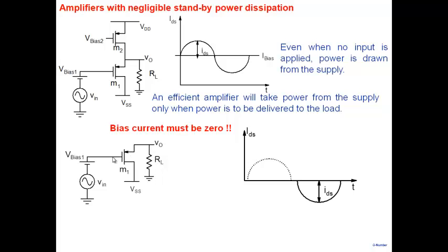If I make this voltage below Vt, right? So for a while in the negative cycle, you see it doesn't conduct. Once the voltage here, Vin, goes below Vt, then it starts conducting. And once it starts conducting here, what we have is basically a common drain stage, right? This is a common drain stage here.